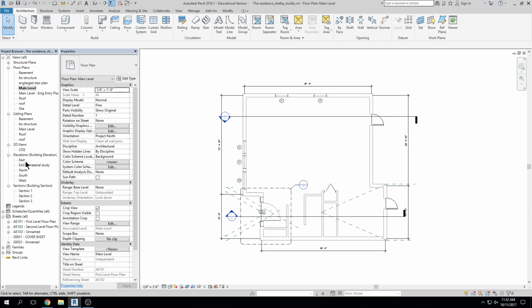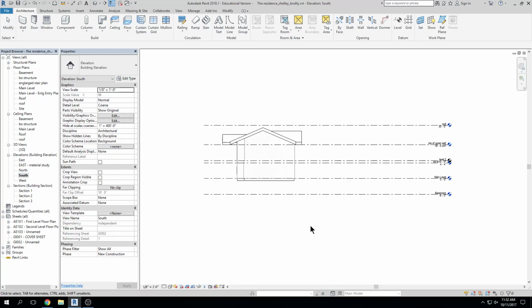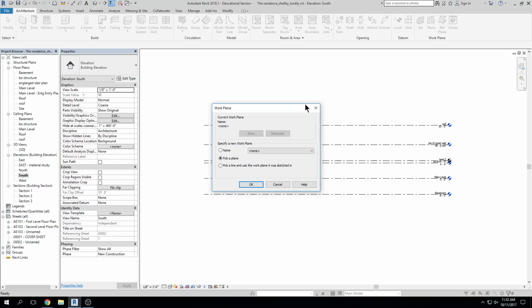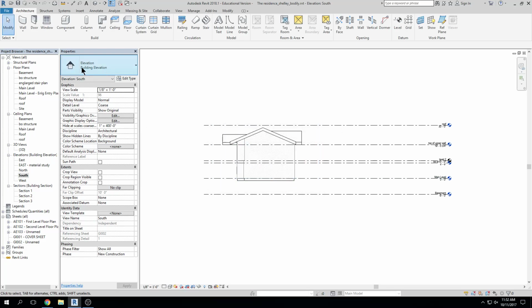I'm gonna go into an elevation view here, and if I hit roof by extrusion, okay, it still says, hey, even though you're in a sectional view, you kind of have to establish where you're going to start this extrusion, because with my building elevation, there's no sort of data marker as to how far away or how close you are to your project, right?